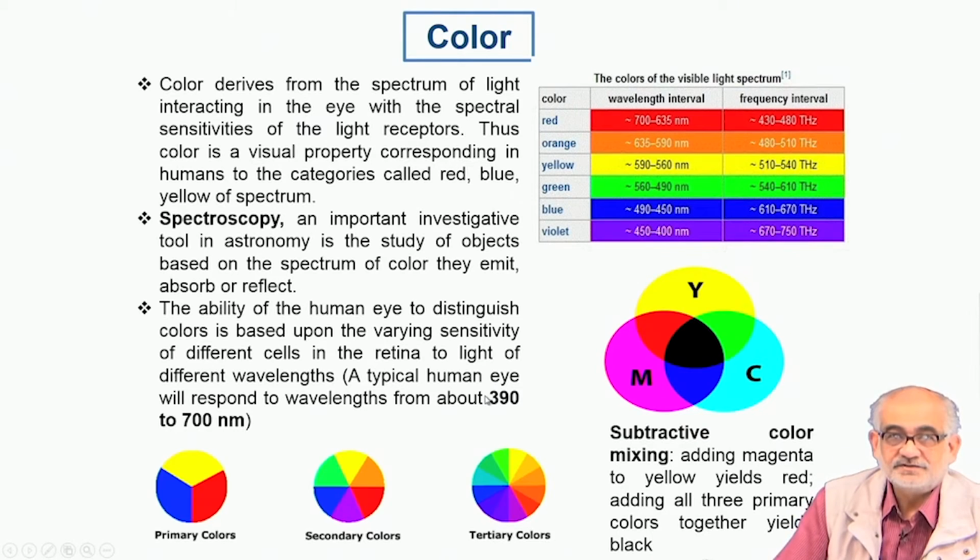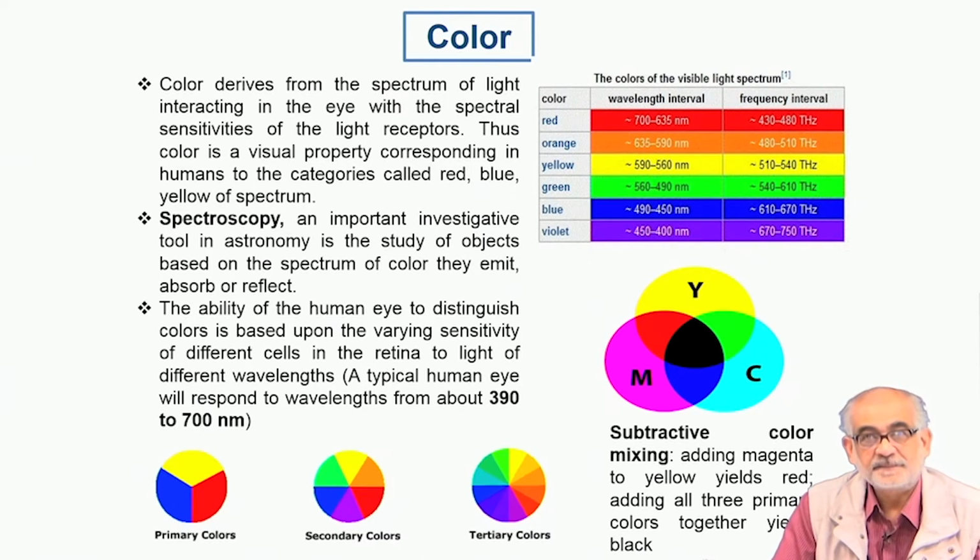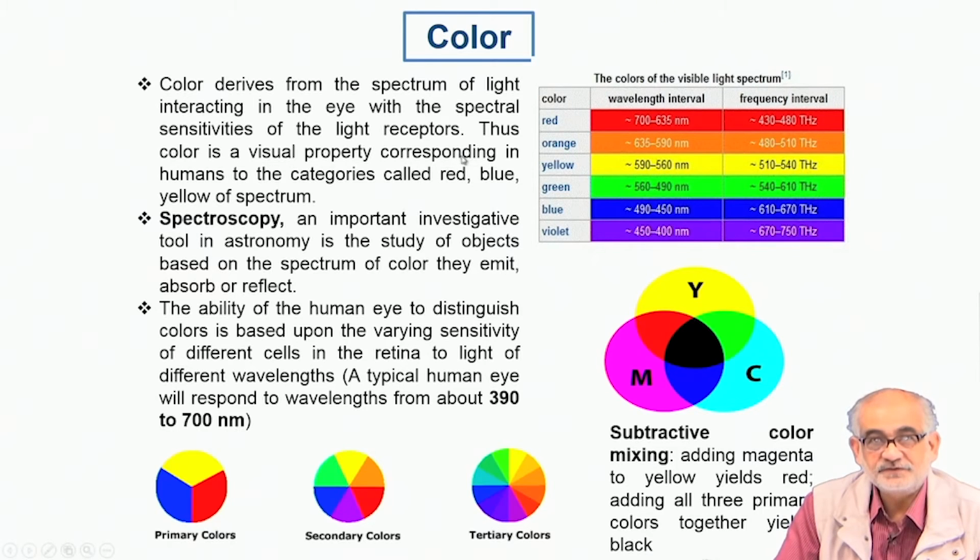Color is a very important engineering property. In fact, aesthetics to a large extent depends on the color and the ability to reflect light. But we must realize that the color that we see is essentially a reaction to the incidence of light on it, which could be white light, a combination of various wavelengths, typically in the range of about 350 to about 700 nanometer wavelength.